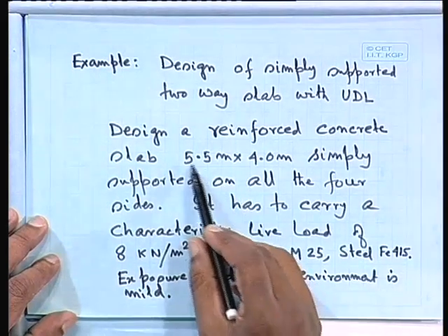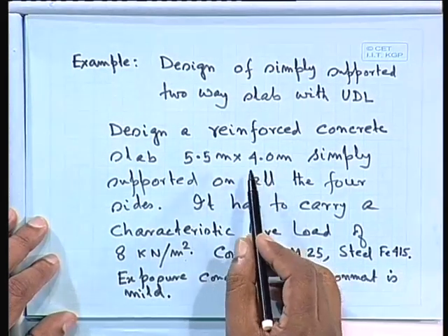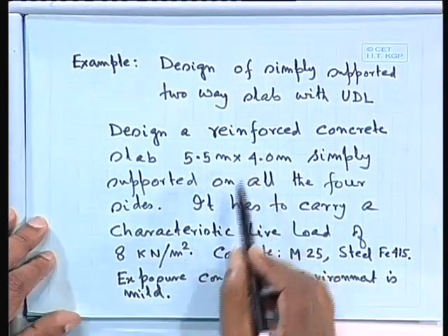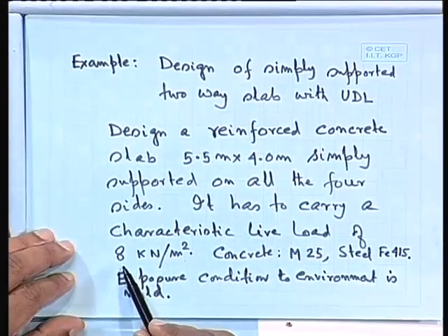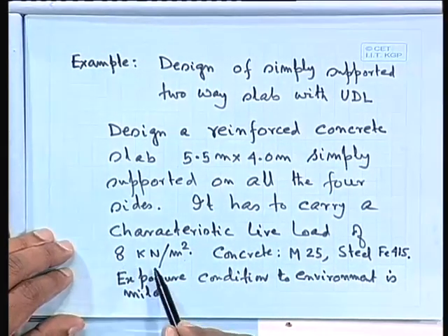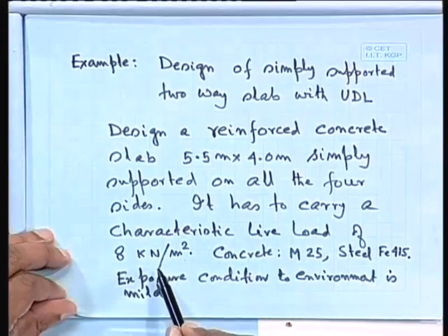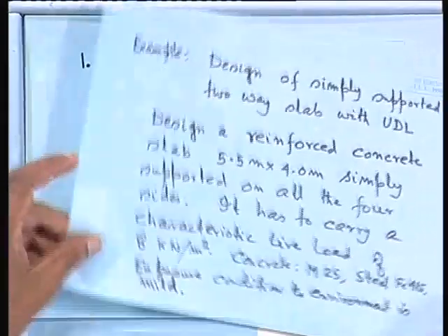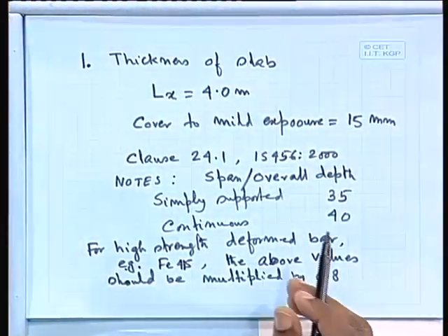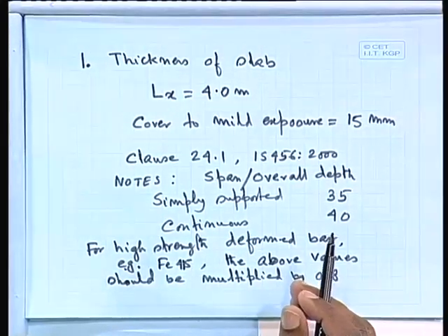So, this is your clause, but let us see our problem. Please note, it is told that for mild steel, up to 3.5 meter, but in our case it is more than that. That is violation number 1. Number 2, it is not 3 kilonewton per square meter, it is 8 kilonewton per square meter in our case. That means we slightly violate that rule.